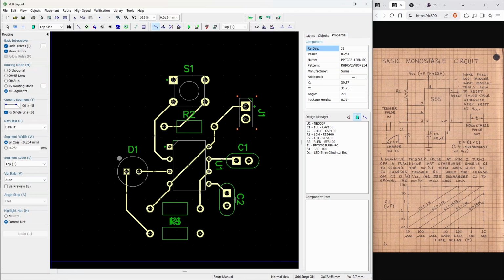It's fine. Having right angles is generally frowned upon, but really it has to do with high-speed systems, high-speed circuits. There's nothing high-speed going on here. We can make these lines look like anything we want, really. But these are just conventions, having these 45-degree angles instead of right angles, and trying to have things flow in a natural way is a good thing. But this looks like I've fulfilled all the requirements, honestly.